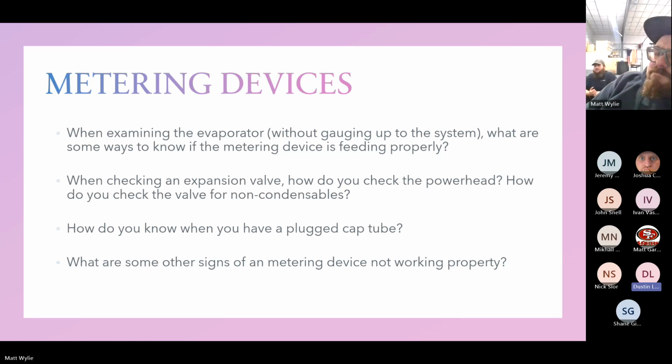Same thing with flood back. If something's flooding back really bad, your coil gets full of liquid, and it can give you a false high superheat. So one thing I always did, before I adjusted the superheat, was valve the case off and let it pump out of the coil for a few minutes, then open it back up and start fresh. That way I don't have either a completely starved coil or a completely flooded coil.